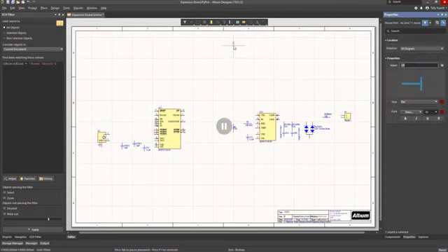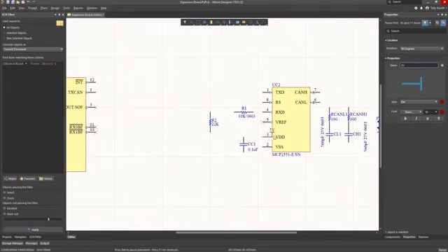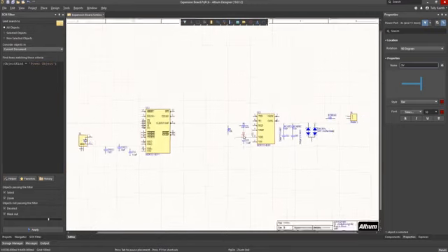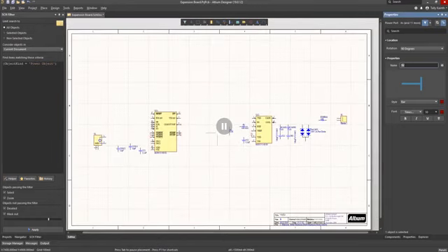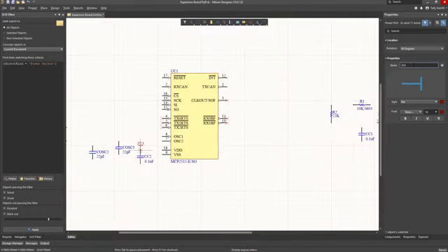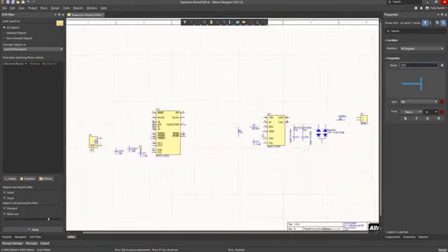Now hit the Tab key and change the name of this port to 5V so that it matches the 5V port on the SBC I/O schematic. Hit Enter and then place the port, if needed, rotating it using the spacebar. With the port still attached to the cursor, hit the Tab key so we can edit the port name to 3V3 and place it just on the CC2 capacitor pin.